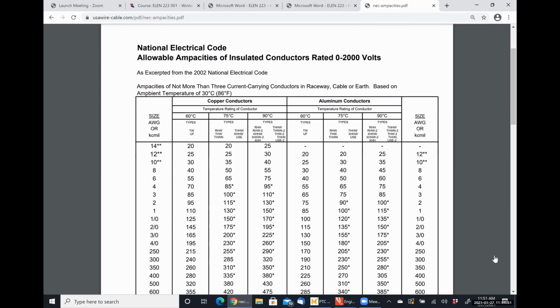we have multiple different wires that we can use depending on how much we allow the temperature in the insulation to rise. What that means really is that different insulations are rated for different temperature levels, right? So if the insulation can withstand temperatures of 90 degrees C before it starts to melt and degrade the wire, then we can use that line.